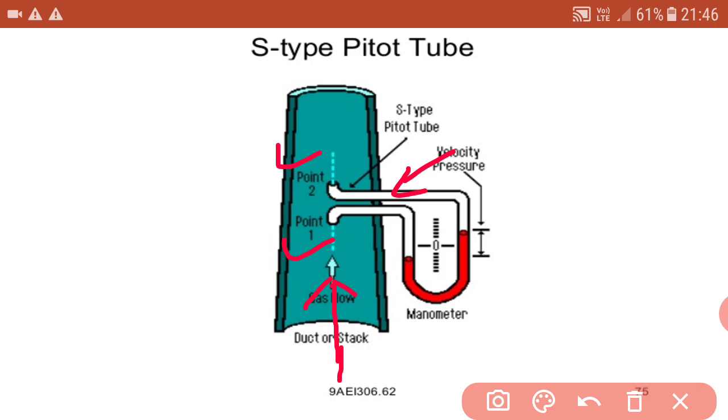A manometer is nothing but a pressure measurement device. So this level is known for pressure. Whenever there is a gas flow, at that time the liquid level inside this tube changes, and by measuring this level using the manometer, we are actually measuring the flow of gas.